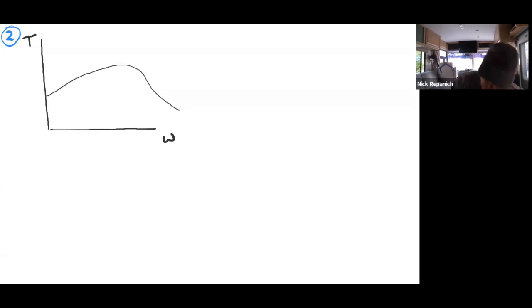When you start to deal with actually choosing motors, here's another graph for you. After you've done all these calculations that I'll show you how to do, the end goal is to go find a motor and see what torque it has over the speed range. So for instance, a combustion engine probably looks something like that. There's some maximum, and remember, torque times speed is power.